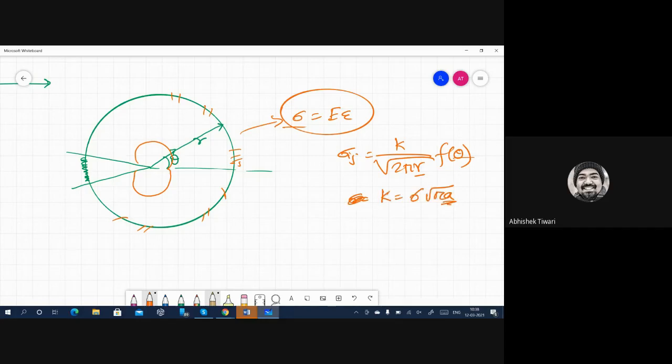a I know is fixed. I'm not modeling crack growth so far, so a is fixed. Sigma I know. Or sigma I don't know, because sigma is what is being called upon. Oh no, this is sigma applied. So sigma applied I know, and from that I can calculate k because I know a, and everything else is known to me. Okay.